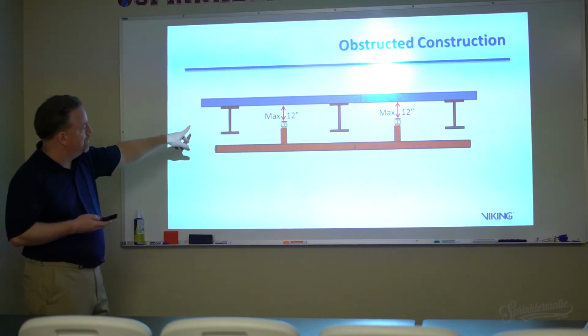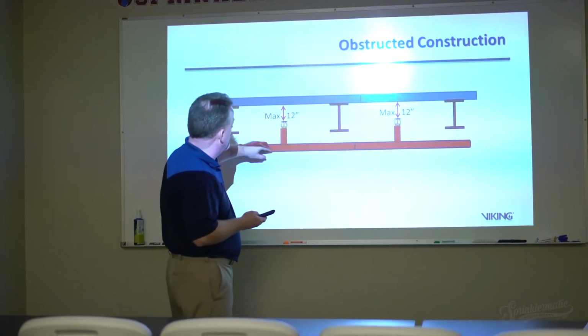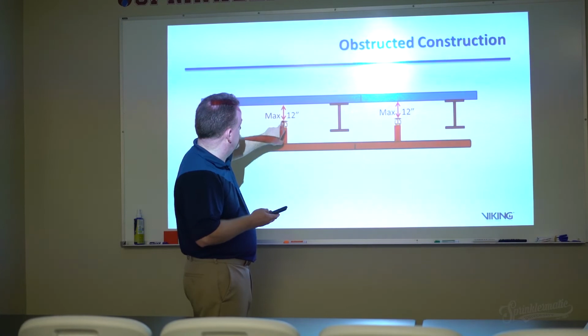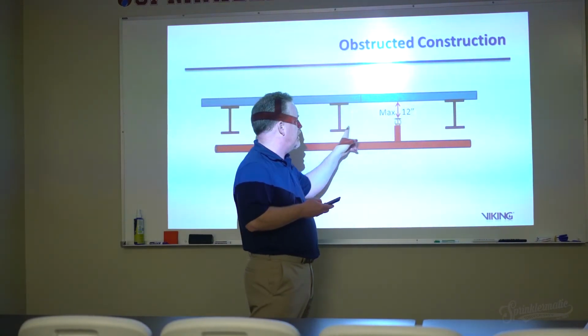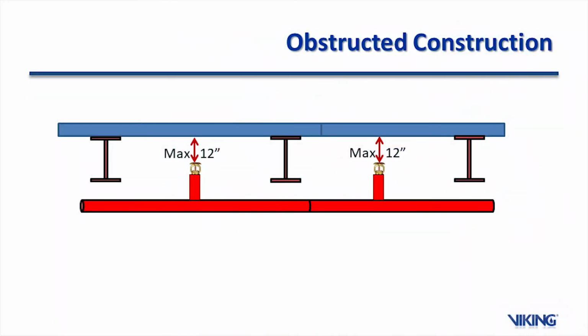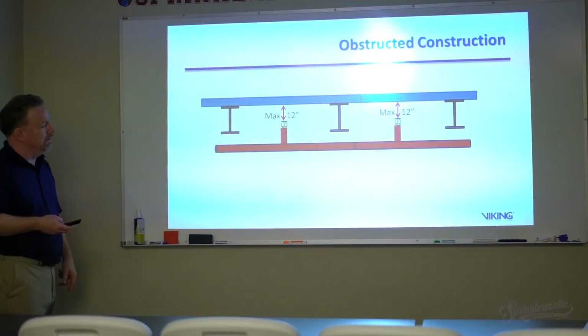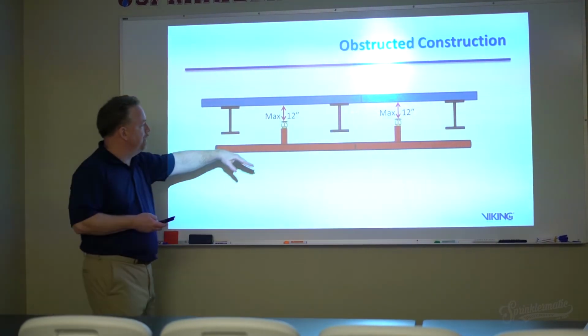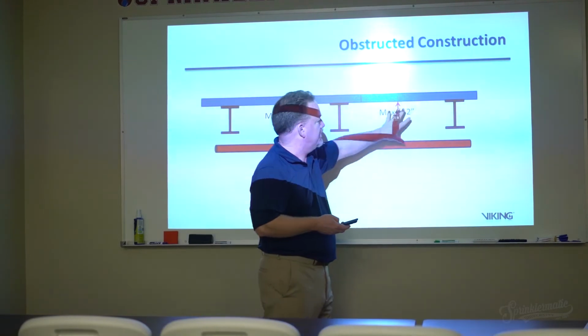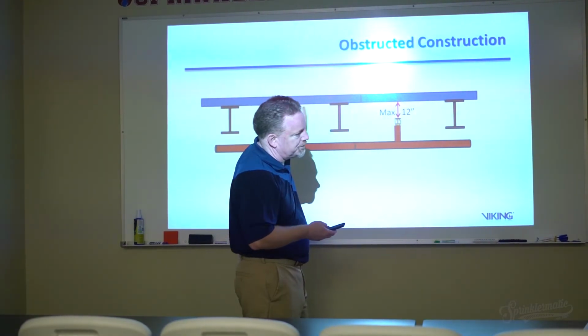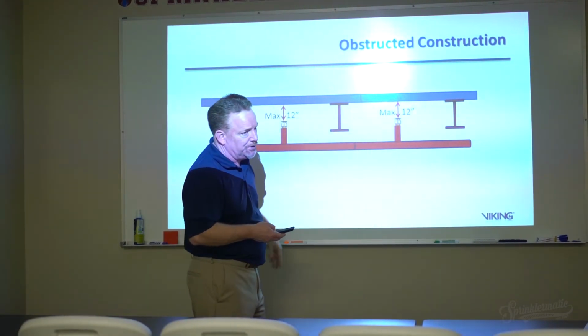And then, if you're going to go up above, then you've got a maximum of 12 inches, and we will talk about how you have to comply with the beam rules here, perhaps, depending on the construction type. So maximum, you could just put them up there 12. In this case here, actually you wouldn't, because you're putting sprinklers in each pocket, so the beam rule doesn't apply here.